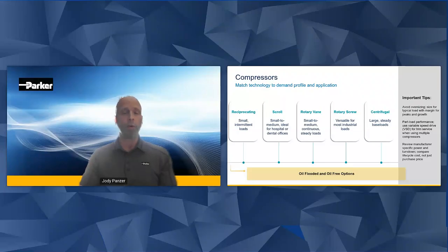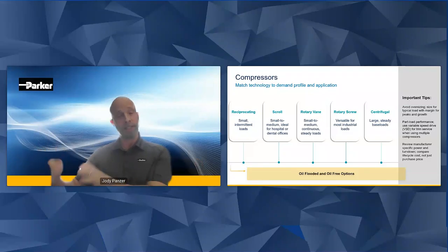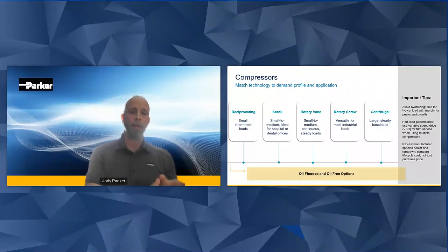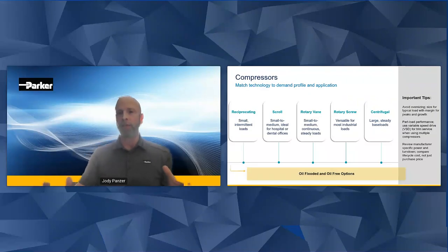With oil-free, there's only oil found in the crankcase, nothing in the compression chambers, typically a two-stage compression system on the rotary screw side, and there's no possible contamination. One thing to note, there is a higher upfront cost, but life cycle cost is going to go down. Your maintenance costs will go down as well. Also, these compressors create a tremendous amount of heat, so there are a couple of ways to dissipate that: air-cooled or water-cooled. Past a certain temperature, water-cooled is the only option.